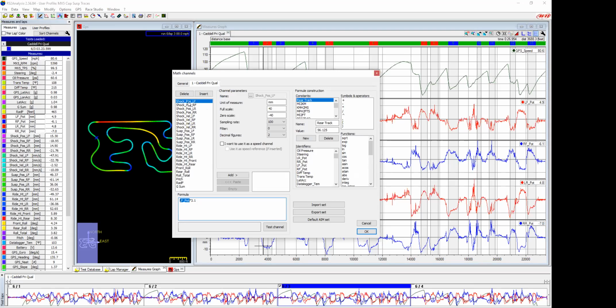But left front shock position, my motion ratio in that picture that we showed you ended up being 3.1 on the fronts, and on the backs it was 3.1. We spent some time to get those things to be as even as possible. So we moved them up and down. If you remember the picture on the back, it actually had a clamp on mount, and we were able to move that around really quickly and use different holes to get these to all be the same.